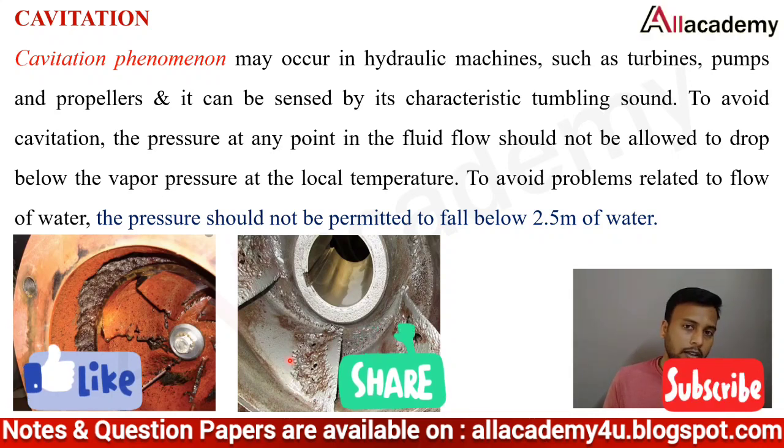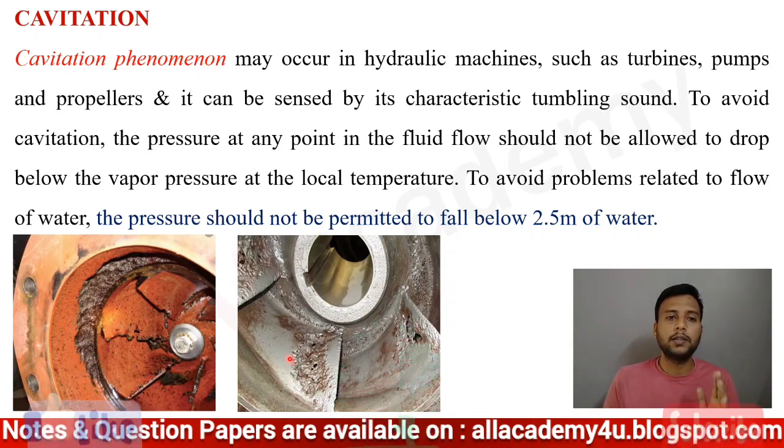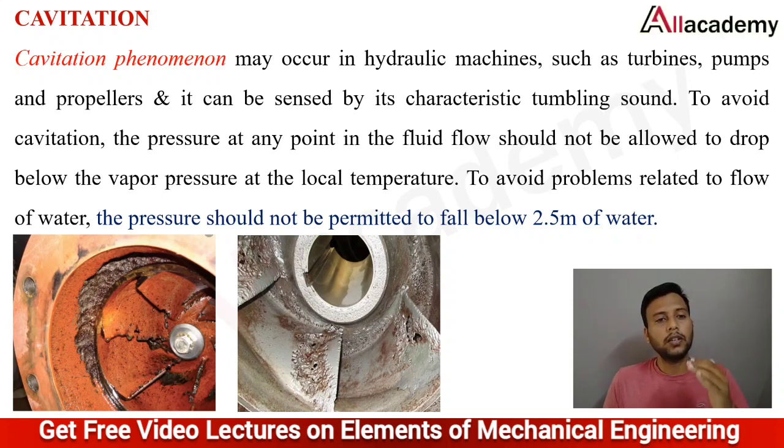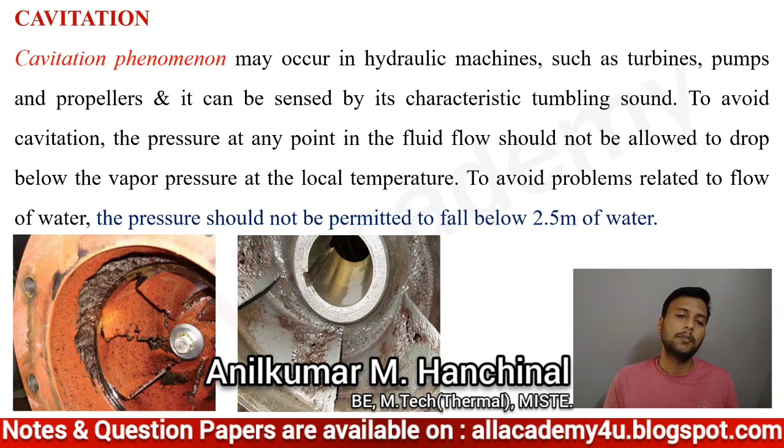So how can we avoid this? We can avoid this problem only by taking care that the fluid pressure does not drop below the vapor pressure. I hope you understood the cavitation phenomenon.